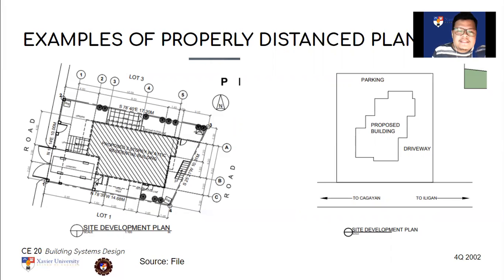Okay. So in all sides, you notice that in this part where it's a little angled with the bearing south 2521 west and 10.31 meters length, the minimum distance maintained here is at 2 meters. But you can actually use 1 meter. You notice 1 meter in the lower left. This is allowed if the land is actually sloping. Okay, so in this case, this part is sloping. So when the owner tries to see the wall that's built, it's not blocking the view. So that's allowed. Okay, so only in these parts, this is 1 meter. Okay, but in the other side, you can allow it to 2 meters. So 2 only also.